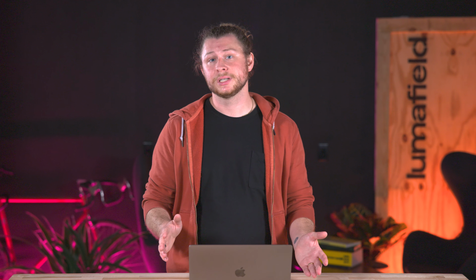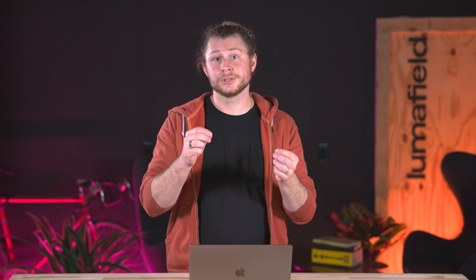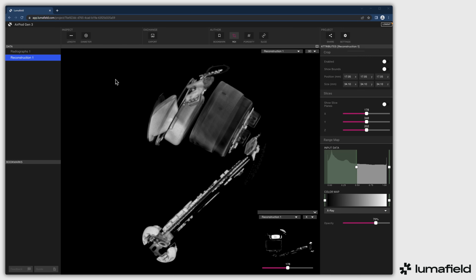Now we're going to move on to regions of interest. Regions of interest allows you to request a high-resolution volume of a certain portion of your larger reconstruction. This is because we cannot display the whole thing in the browser. It's too big. So this tool allows you to get the highest resolution data of a small portion of your part. We're going to look at these AirPods and isolate a specific portion of them and request the region of interest back. The region of interest tool is very similar to crop.